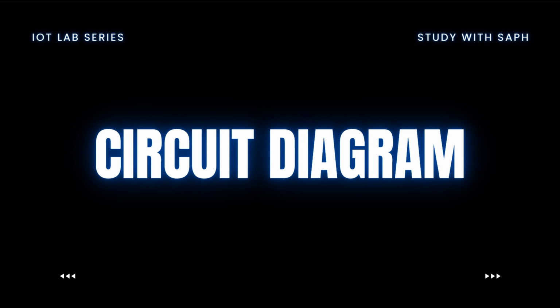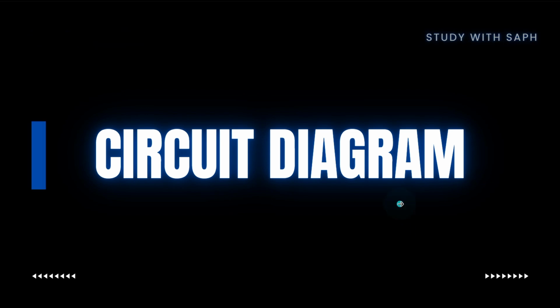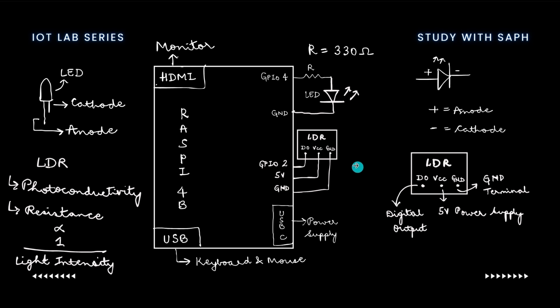Let's now have a look at the circuit diagram. When you look at the LDR sensor, it is basically a 3-terminal device, and the various terminals are as follows. We have the VCC, which is connected to the 5-volt power supply of the Raspberry Pi. We have the ground pin, which is connected to the ground terminal on the Raspberry Pi. And finally, we have the third terminal, which is the D0 terminal, connected to the digital output.